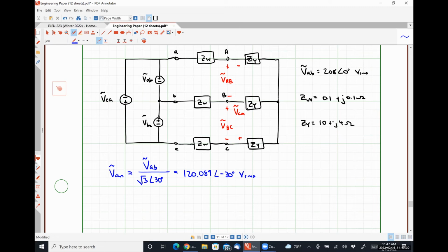So that's a very, very common configuration. If you look at the panels in this building, I know the ones in Bogart actually say it on the outside. It'll say something like 208/120Y. That's telling you what kind of three-phase power you have. If you have a Y configuration, you effectively always have access to a delta configuration too, because it's just looking at the voltages in a slightly different way.